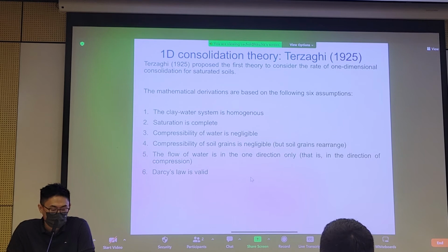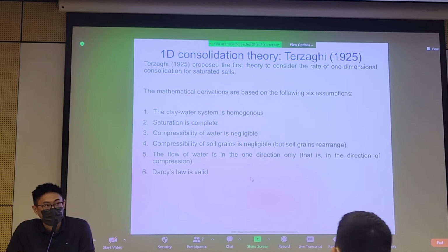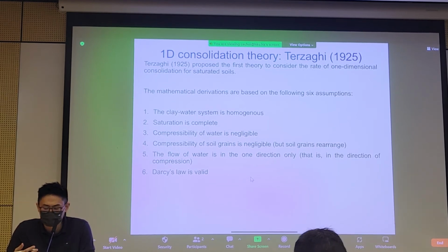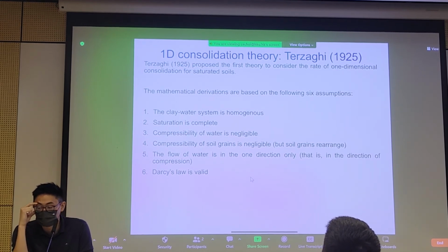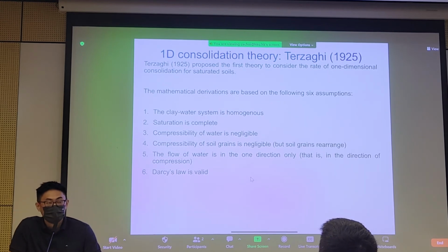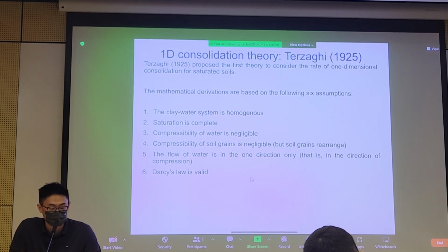What you do need to know is how to use the equations to calculate the degree of consolidation at a particular depth for different times. But there are some other things I do want you to understand, and this is the basic assumptions related to Terzaghi's 1D consolidation theory. You should at least know what are the limitations of the theory. If you understand the limitations, then if you get discrepancies between field data and the values you calculate, at least you'll be able to explain the differences.